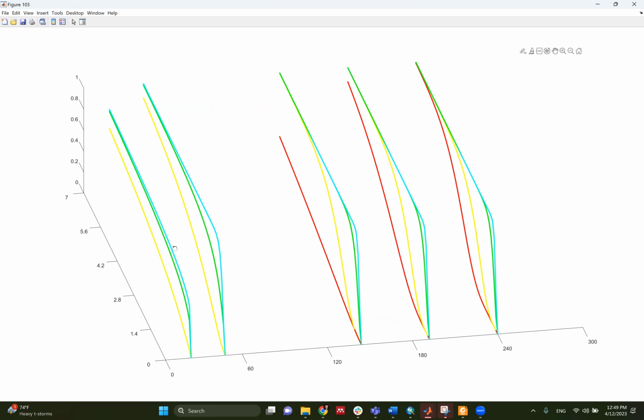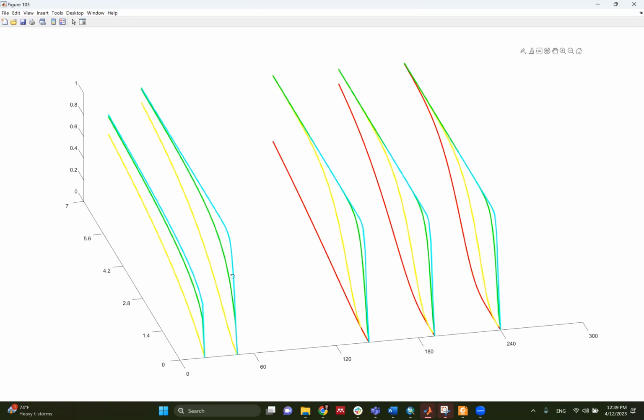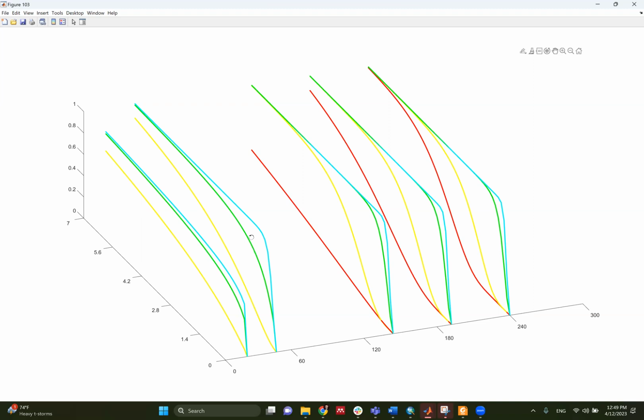I'm just going to show you how the flood fragility looks. So you have these at flood duration 1 day, 2 days, 4 days, 8 days, and 10 days. How does it look? Basically, you cannot see damage state 4, the red line, in these 2 fragilities, which means that the building is not going to reach damage state 4 with a 2-day flood duration, because damage state 4 is structural damage.